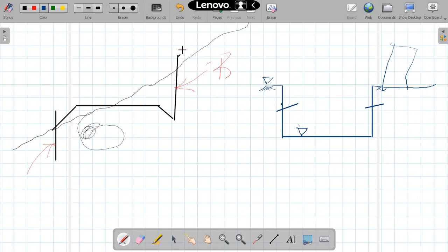Here also they have been maintained at different levels. This is one level. Again at the road you'll find this is another level. And here the normal ground level again. So here earth surfaces have been maintained at different levels with the help of these retaining walls. That is how these retaining walls will help us in maintaining the ground surfaces at different levels. So that is the purpose of providing these retaining walls.